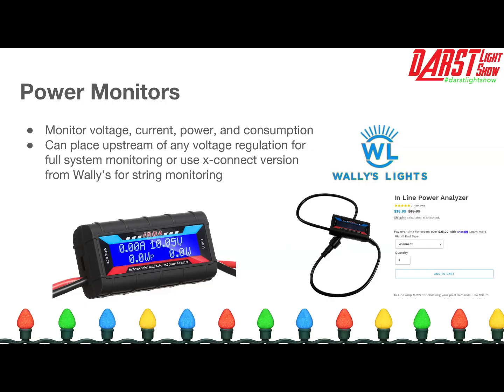Now, a lot of modern controllers have power monitoring built in, and they're giving you a calculated estimate. If I'm personally looking at full load of what my show is, if I want to measure it at full white, or I want to see what is the peak current usage throughout my entire show, I'm going to use this one over here on the left that I put upstream so I can get a full picture of, with all of the wasted power and all of the inefficiencies considered, what am I actually using.